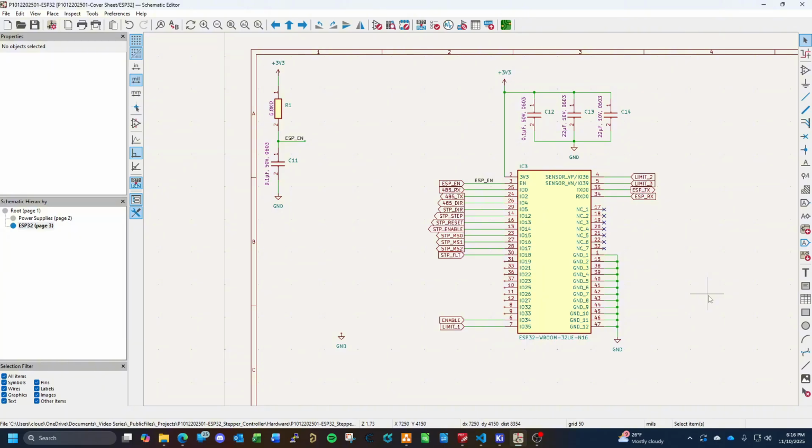I'm not really pushing for that with this design because, again, this is just basic prototyping, experimenting. I don't want to make anything too overly complex. The good thing is this chip will shut itself down if it detects a problem like overheating or overcurrent. It will go into protection mode, and I think that would kick on a fault signal. So we have that fault. So that's our stepper motor. There's a lot of inputs and outputs, a lot of controls on that. That's why we're pin heavy.